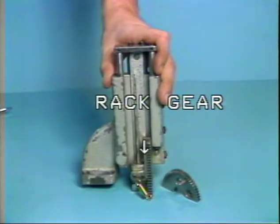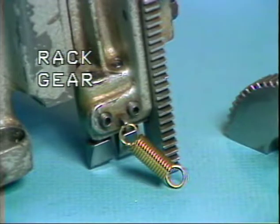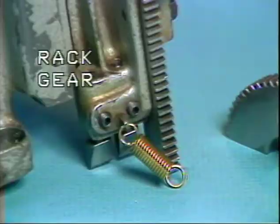Located here is the straight rack gear. The rack gear is attached to a sliding column. The rack gear is meshed with a half-circle gear mounted to the friction clutch. The purpose of the rack gear is to transfer the feed cam rises and falls to the half-circle gear.